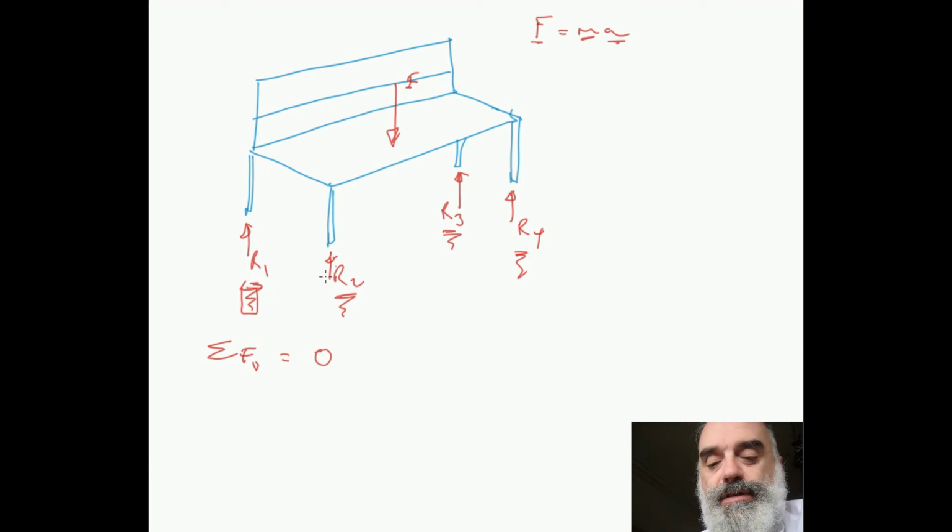that those springs are linear elastic springs, and as this sinks down, the ground gets compressed more and then produces a greater reaction until we reach an equilibrium point where all the forces in the downward direction are reacted by the compressed ground reacting in the upwards positive direction. And although the bench may sink a few inches into the ground, it will reach a point at which equilibrium is restored. And we said that for vertical equilibrium, all our actions needed to sum up to 0 for that to be in static equilibrium.